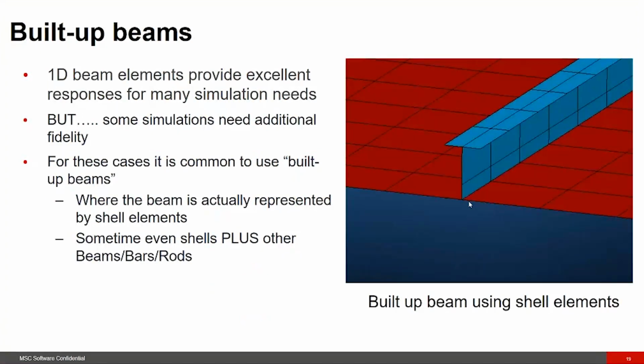For that, we are introducing what is called the built-up beams, in which case we are going to create a profile of this cross section using the sketch tool, and then use that profile to sweep along a curve to create these beam elements. I mean, when I say beam elements, beam-like structures by shell elements. It's not that we need to have only the shell elements.